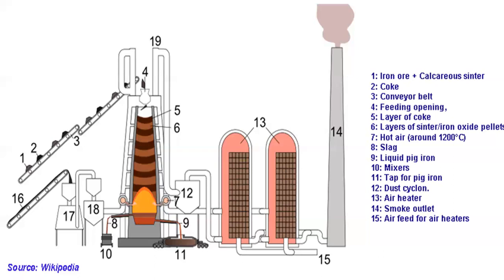However, based on information obtained from 6 efficient hot blast stoves and blast furnaces around the world, the average primary energy requirement for a blast furnace system is reported to be 1.8 gigajoules per ton of hot metal for the hot blast stoves and 11.6 gigajoules per ton of hot metal for the blast furnace itself. Now, there are very few alternatives to this blast furnace in the integrated steel plants. Direct reduced iron and smelting reduction technologies offer an alternative to blast furnaces for iron production and are gaining importance day by day.